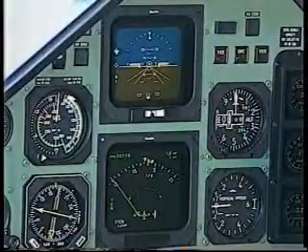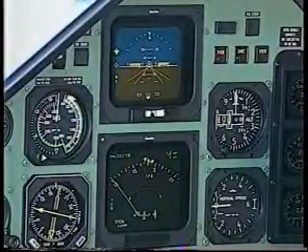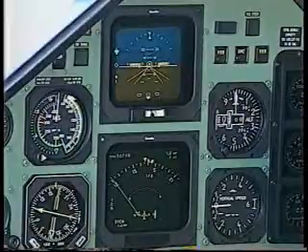Now, what can go wrong with the system? The short answer is not very much at all. The equipment has few moving parts, and everything has a backup power. However, there are a few abnormal situations which can arise, and we'll cover them now. Firstly, as I mentioned earlier, all 4 display units are driven by a single symbol generator. If it's not your day, and it fails, you will have to fly under standby instruments. But, if a display screen fails or is unusable, simply press the EFIS swap switch here.